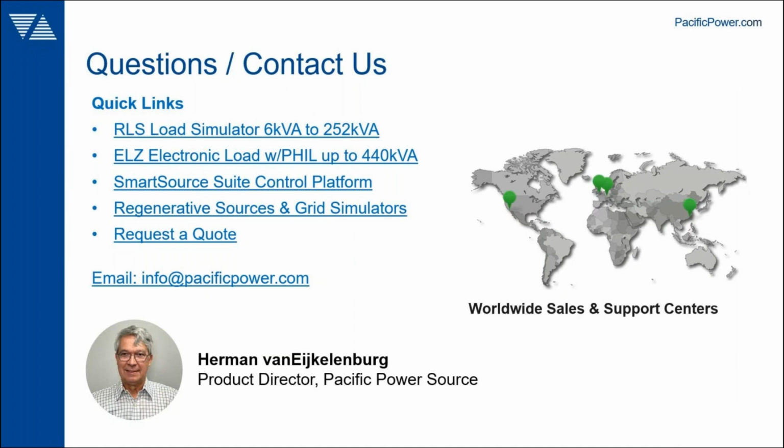Yeah, good question. The browser potentially allows you to operate remotely if you want. It doesn't have to be right where the equipment is, and that can be risky if you don't know what's connected to it. So there are a number of layers of protection that you can set on the browser function on the power on the load. You can set it to read-only mode where you can only use it to monitor. So if you wanted to see the measurements or the scope function displayed, you could do that remotely on the web browser or on your tablet or on your phone, but you couldn't control anything. You would have no ability to change any settings or turn the output on or off; it would be monitoring only. That's one layer of protection.